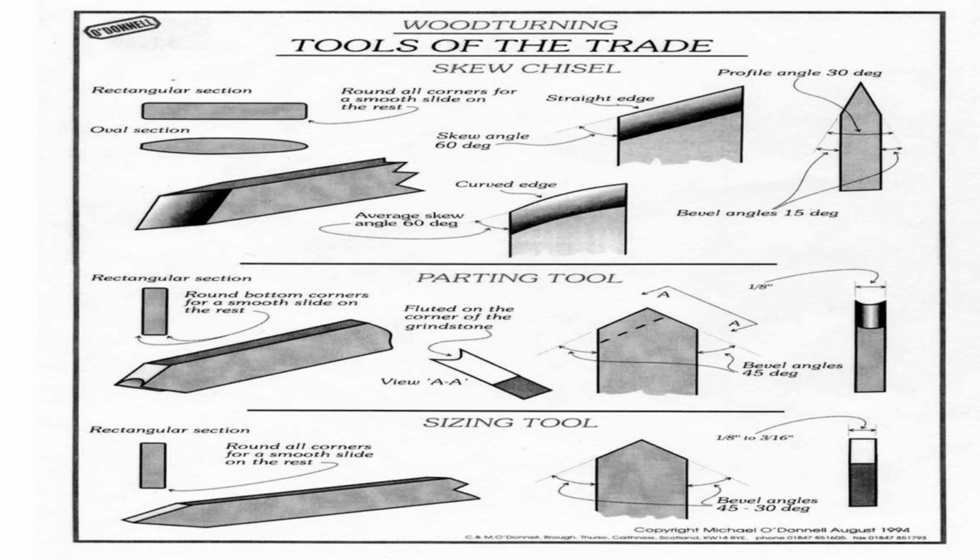Skews are, I've taken one course from Alan Lacer, and you know, he lives and dies with the skew. I mean, he's obsessed with it. It really does leave a nice shearing cut, but it's probably the scariest looking tool in the set that you've got. Again, the key is that as you use the skew, you're not gouging the wood away from the surface. You're really just shearing the fibers at the surface of the wood, and you end up with a very, very smooth cut.